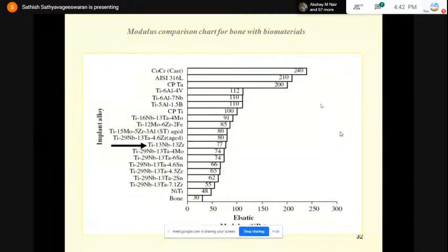It is just resembling a pancake-like structure. If you are visualizing it, it will be exactly like a pancake. And this splat will have a very weak grain boundary. For example, if a crack is initiated at this splat, the crack will propagate in a rapid manner, and finally it will lead to failure of the coating.